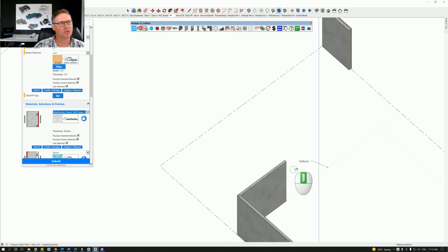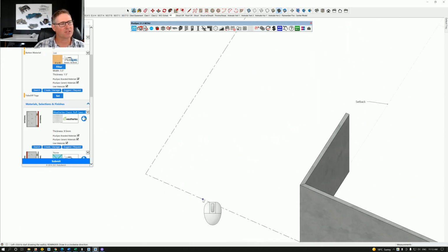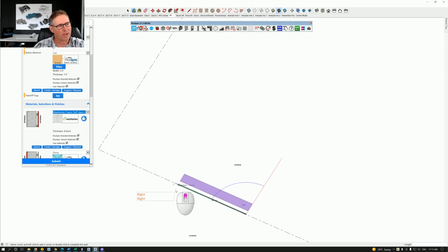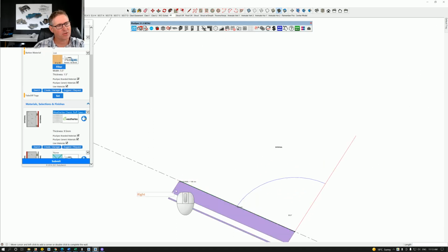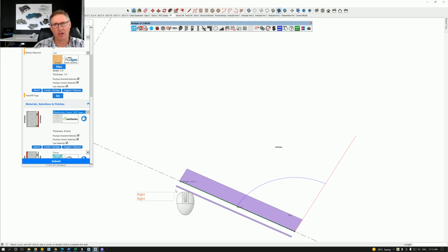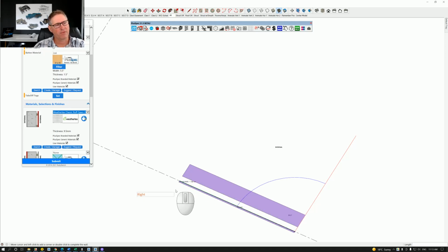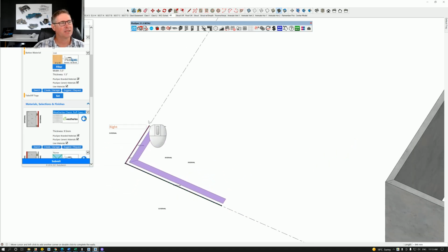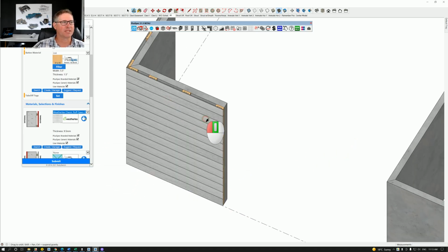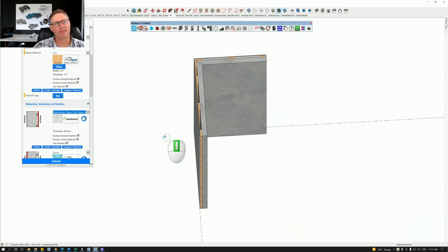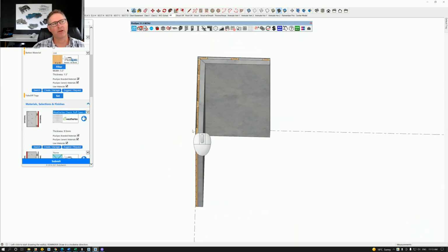However, what I do know is that if we did want to draw from the outside of the wall, we need to use our right arrow button. You'll notice that it's justifying where the wall is drawing from: internal wall, from the outside of the load bearing, or the XY or pitching point, from outside of batten or outside of cladding. Therefore, if I draw from here to here, I've actually allowed for a potential finish. So even though at the initial stage of design you may not have figured out what type of finishes, my advice is to actually choose the worst case scenario.